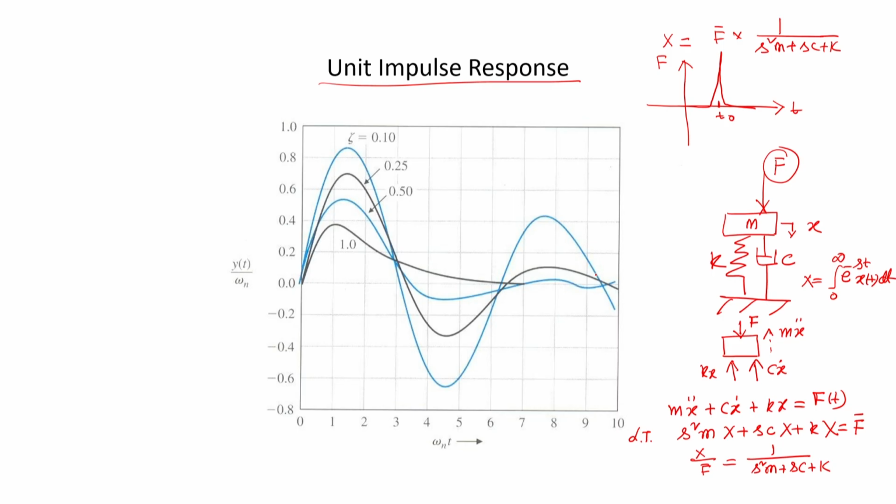And we can see here that if this damping becomes equal to 1.0, then there is almost no oscillation in the system. This is related to what we call critical damping of the system, but this critical damping we have to define in terms of zeta, actually not the damping constant but the damping ratio.